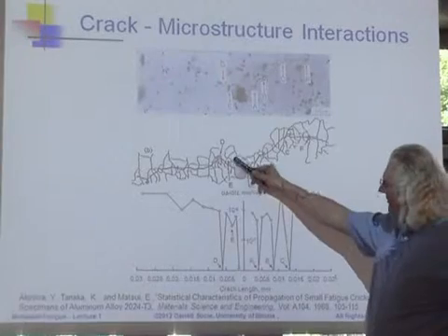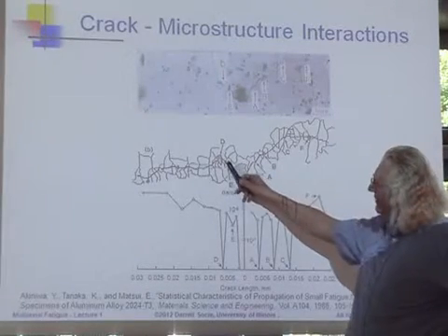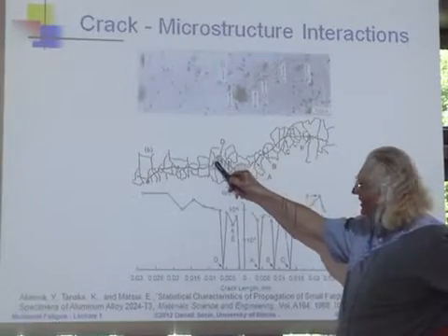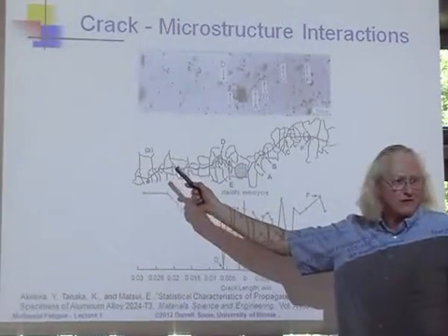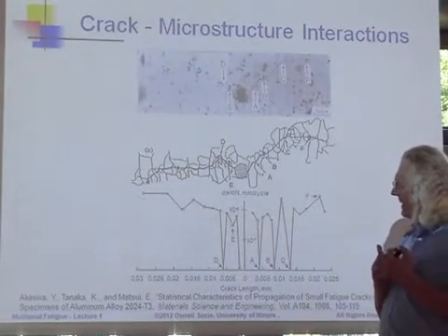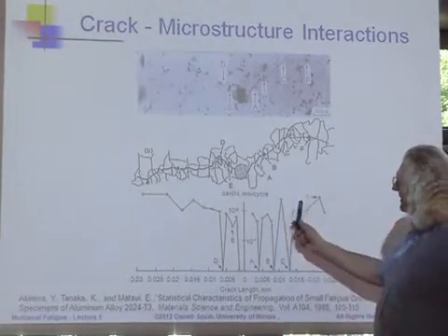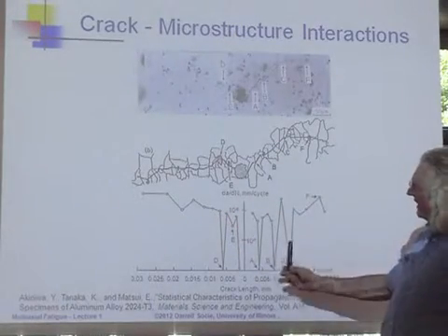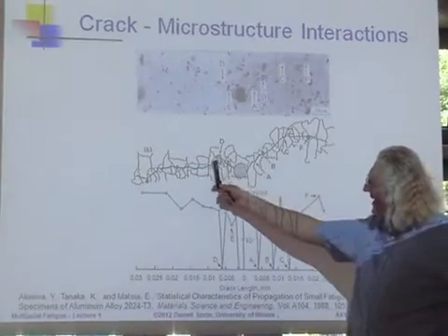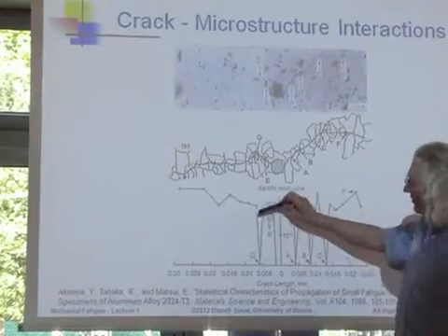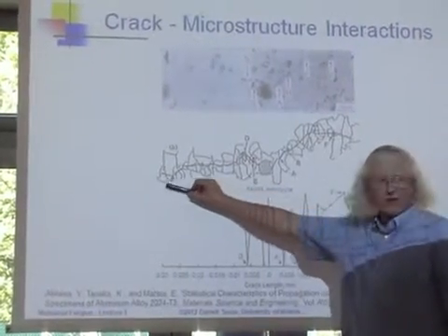And we can make the same picture across here. Of course, this crack is growing and tries to hit this little inclusion. When it does that, it slows down for a little while and tries to grow around it. So here's even more complexity in the real fatigue process. But the other thing to notice is, yes, there is a lot of complexity in this process, but by the time you get a size bigger than the microstructure, then the crack grows at a slow, stable, predictable rate.